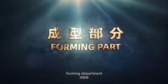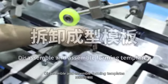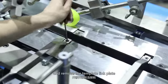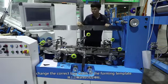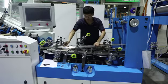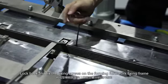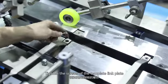Forming department. Disassemble and assemble forming templates and remove the template link plate. Remove the fixing screws on the fixing frame of the forming template. Change the correct bag width of the forming template. Lock back and fix the fixing screws on the formwork fixing frame. Tighten the screws of the template link plate.